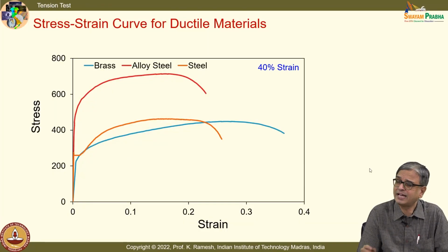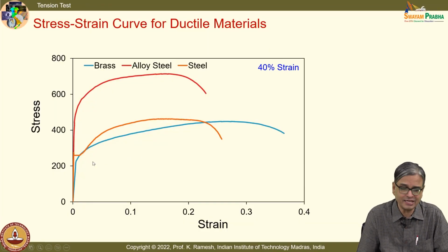See, mild steel has lower yield point. Well, he has looked at it that this has a lower yield point and this apparently has capacity to withstand large stresses. And you have a difficulty. Can you locate where it demarcates from elastic to plastic? There is no demarcation. There is a clear demarcation in the case of a mild steel, which is absent in the case of an alloy steel. And if you look at the maximum strain, they are similar. There is a small dip in this.